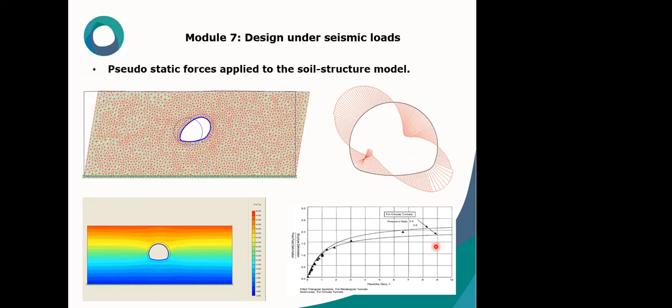However, as you may know, these methods are very complex, time-consuming, and costly. For this reason, in the design process, we use simple methods such as pseudostatic ones. But the point is that pseudostatic analysis methods for above ground structures are completely different from those used for underground ones. It is due to the fact that their dynamic responses are not the same during excitations.